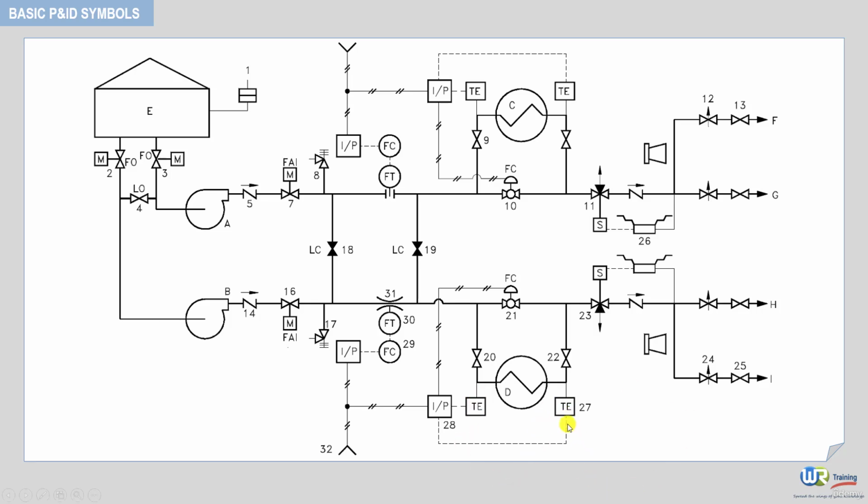This is the case of the lines connecting the temperature elements to the pneumatic to current converter. And finally, if you recall, we learned that the slashed line in a P&ID represents a pneumatic signal. This is the case of these lines. So, this is it. Quite simple, isn't it? We have successfully identified all the process equipment and the flow path. In the next video, we will have a closer look at the different valves depicted in this simplified P&ID, examine their position and their failure mode.